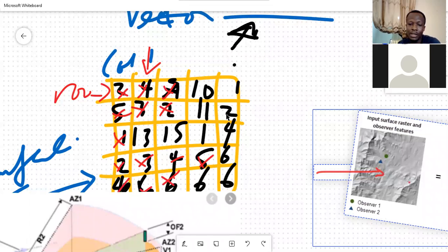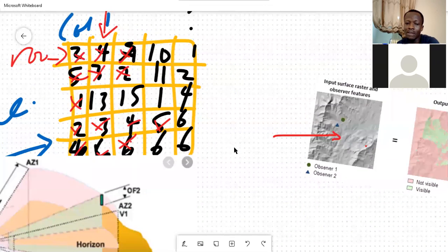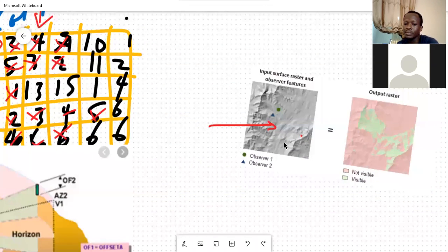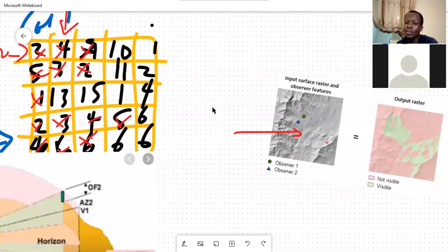Israel, are you okay? Yes, please. So you have to combine different layers and then cost them. You create what we call a cost surface. Is that okay? And then you combine it, add them up. You use the raster calculator to do that.